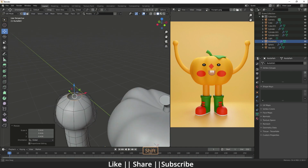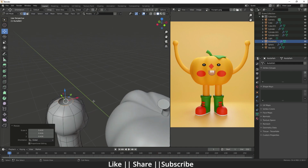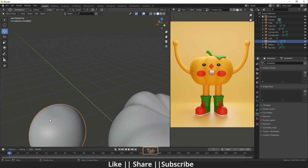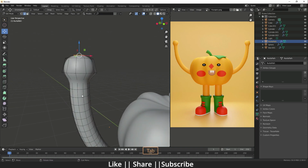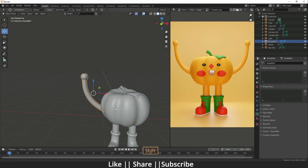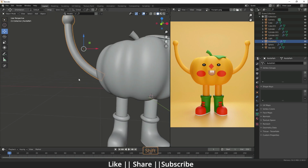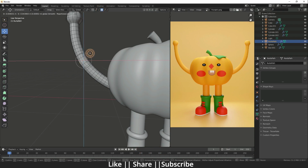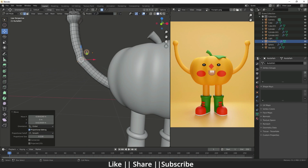Okay, and then we'll press F3 and search for grid fill. Yeah, so it will fill like this. Okay, and we'll add one edge loop in between here, so it will look like a more sharp area from here. And if you want to move this elbow a little bit outside, you can move it from here. Otherwise you can enable the proportional editing, so it will move very nicely.